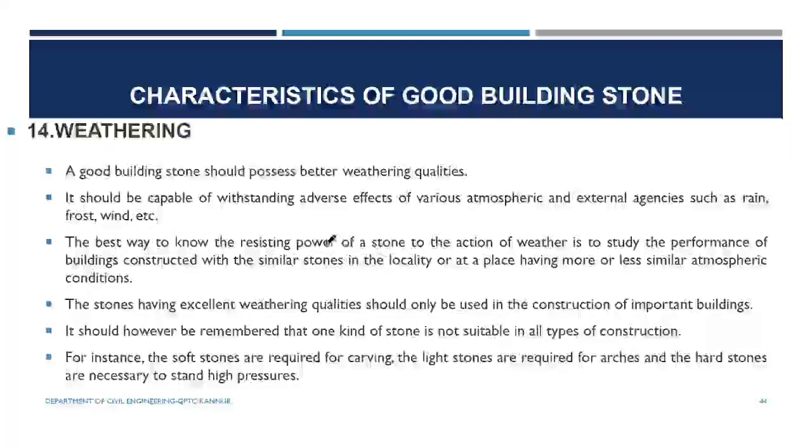The best way to know the resistant power of a stone to the action of weather is to study the performance of buildings constructed with similar stones in the locality, or at a place having more or less similar atmospheric conditions. Just go and see your neighbors. If you are going to construct a building, just go and check how the stone is behaving at Kannur Government Polytechnic. Just take a visit there. Stones having excellent weathering qualities should only be used in construction. You have to keep that in mind.